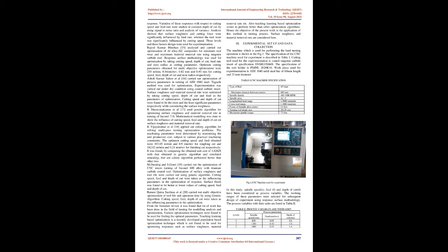M. Nalbant et al. [11] investigated the effect of insert radius, feed rate, and depth of cut on surface roughness in turning of AISI 1030 steel using TiN-coated tools. The Taguchi method was used to obtain the optimal parameters in the turning process. Orthogonal array, signal-to-noise ratio and analysis of variance were used to obtain the performance characteristics. Insert radius followed by feed rate were the significant parameters in the optimization of surface roughness.